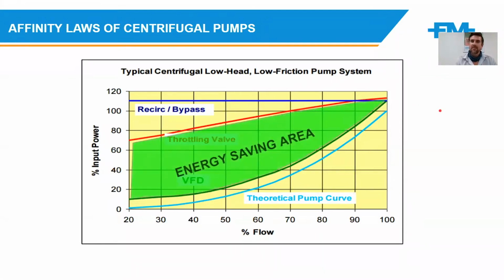However, the energy saving area is in the variable speed part of the drive. So if you can just minus a slight bit of rotational speed off the system, instead of choking a valve, the energy saving that you could yield is quite substantial.